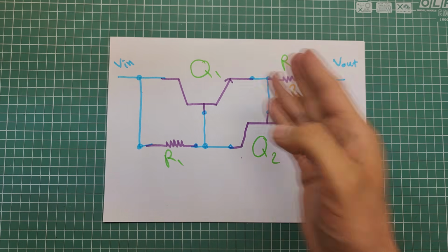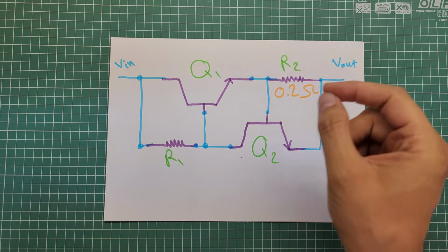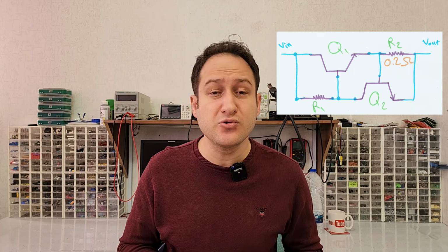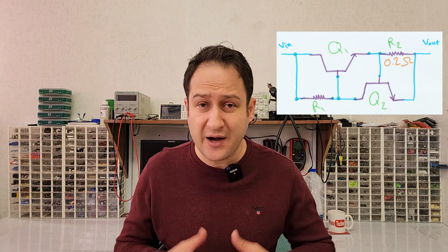So, the voltage on output will be decreased to keep the delivered current to output constant. If the load needs more current, this circuit will try to reduce output voltage to control the current. So, this process will result in a balance which will lead to a constant current equal to the current threshold.